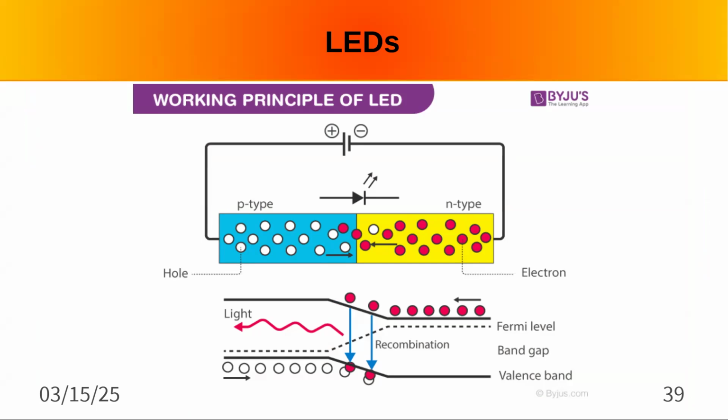And because it takes energy to get those electrons to cross the barrier, when they get across and recombine, and that's what this bottom chart is trying to show. It's a little confusing. But when they recombine, they lose that energy. So it has to go somewhere, it gets dissipated. So depending on the amount of that energy, what that band gap was, will determine the frequency of the light that's emitted, and also how much of it is split between phonons and photons.